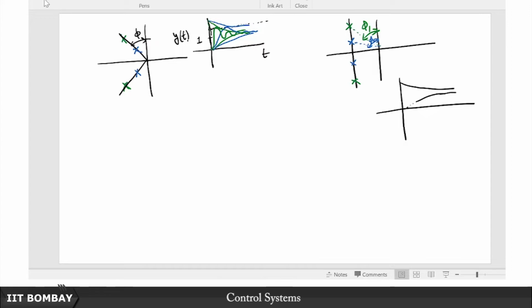And that fits in very nicely with the picture, because now the blue fellow has lesser percentage overshoot and also attains its peak later. So if I draw the blue step response here, it would look something like this, and if I draw the green response here, it would obviously attain a higher percentage overshoot because of the lighter damping, and it would also attain its peak sooner. So this is in all probability what the response of the green system is going to be like.